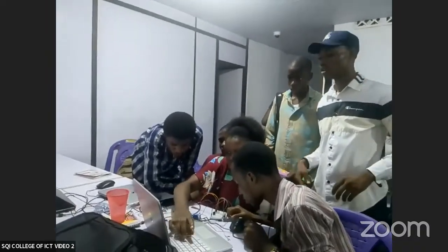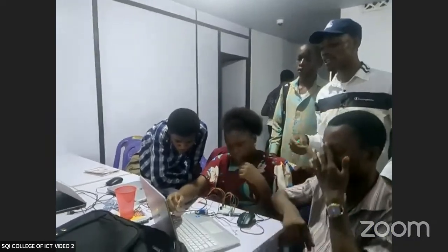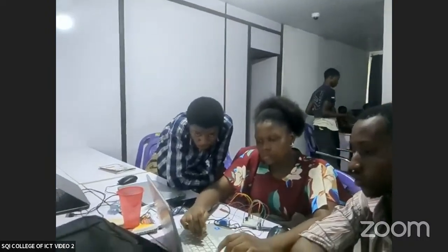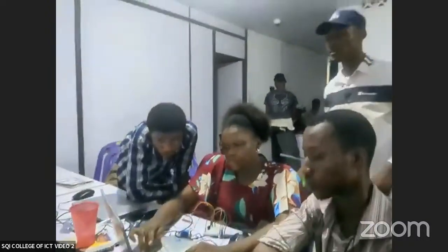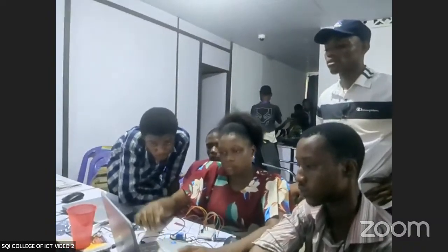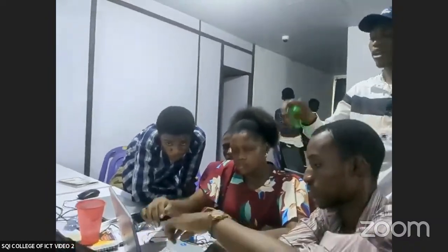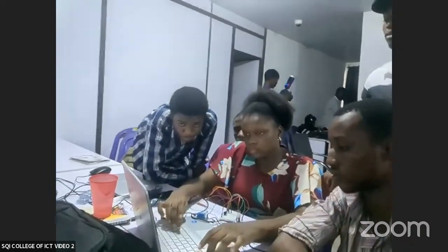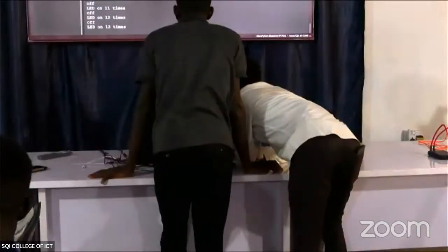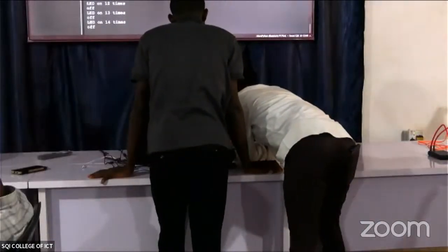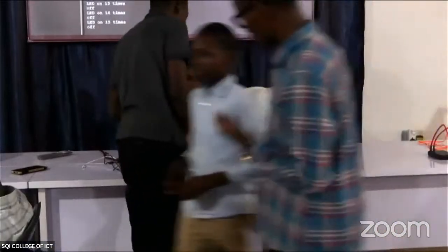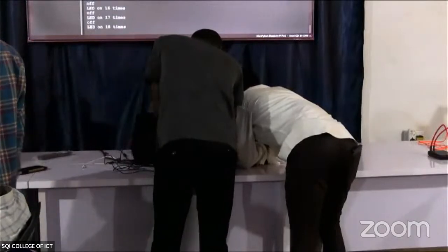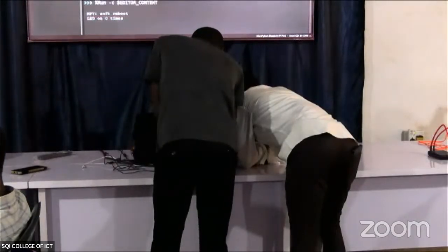Hold on, run. It's not switching. It's meant to come on once you connect to this. The thing is, it's a low level trigger relay, so you are supposed to switch it off for it to come on. Even now, it's not switching. When it's connected to this, is it meant to turn on any of these LEDs? Yeah, that's the thing. It's supposed to be off.